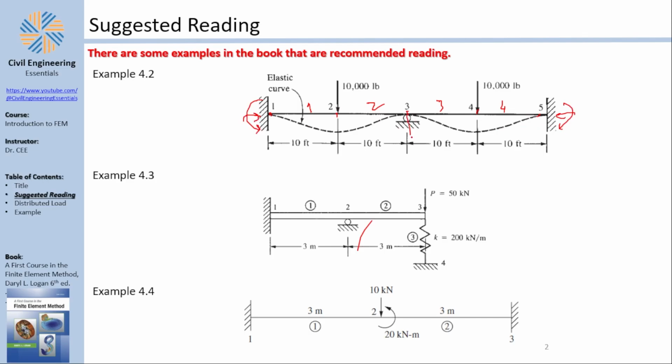And here you have no movement. So in the end, what I'm expecting is that after you reduce your stiffness matrix, you would have 2 rows here, 1 row here, that's 3, and 2 rows here, that's 5. So you would have a system of 5 equations with 5 unknowns. That's what I expect. This example is interesting because it mixes both beams and springs.